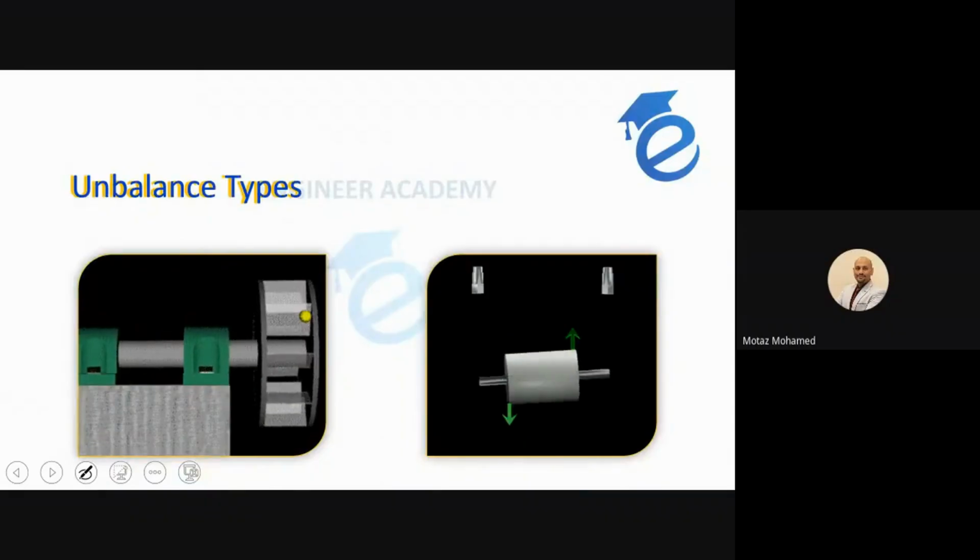As I told you, many measurements could be taken just to make sure that you have unbalance or any other defects, because normally, as we all know, unbalance shows up as 1x and a sine waveform, but it's not only the case. I'm going to tell you that all the defects literally generate 1x. Then you need to take extra measurements, whether it's phase measurement or any directional measurement or any kind of measurement, just to make sure about unbalance. And according to this, you take the proper action for correction.